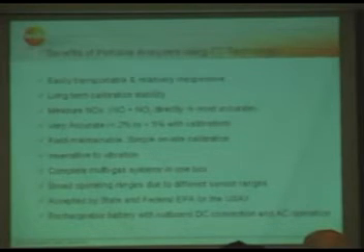That means the EPA and the ETV used our analyzers in comparison with reference technology at different applications, like a gas engine, a boiler, a turbine with different fuels, and they compared the readings and made sure our analyzer is as accurate as the reading of a reference technology, and they verified that this analyzer with electrochemical sensors can be used for those applications for compliance testing.